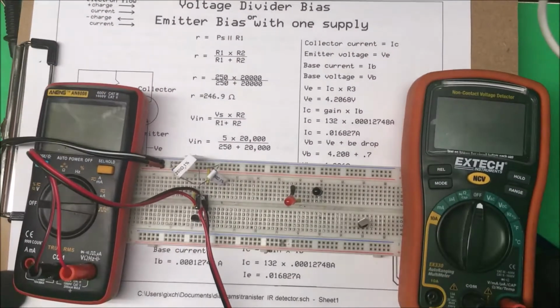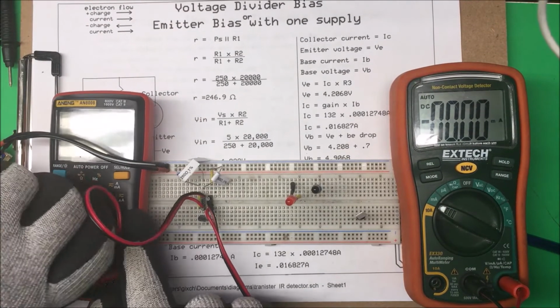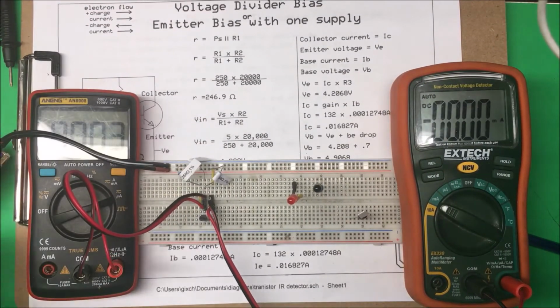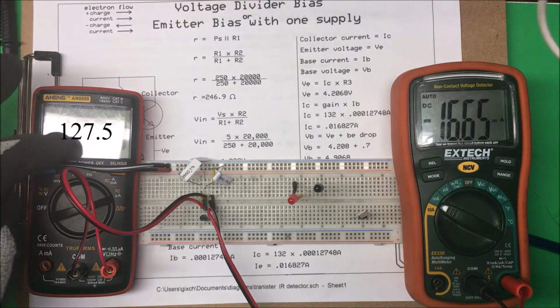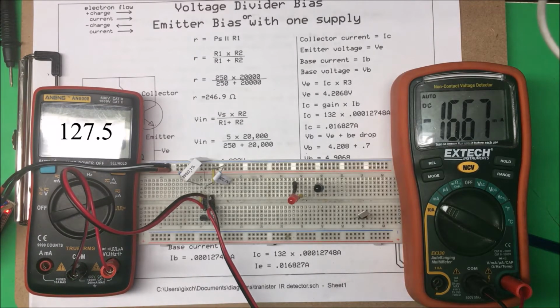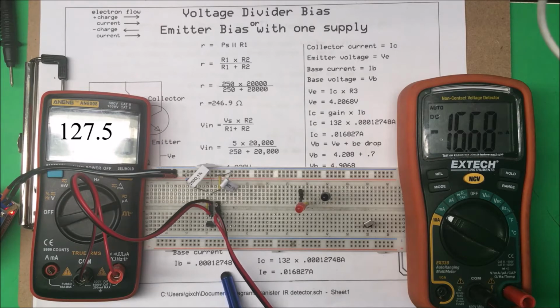So I set it up right here. I'll put this at milliamps, and this one I'm going to set to microamps, and I'm going to turn the voltage on, and we've got 127.5 microamps, and it says here we had 127.48, pretty good.